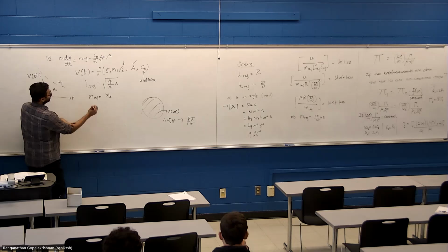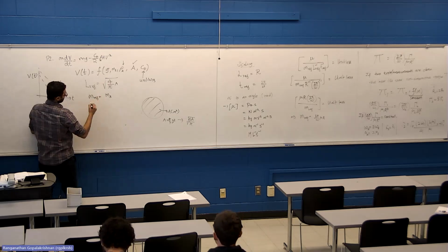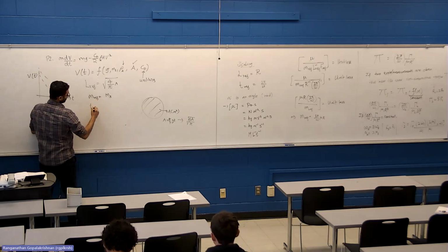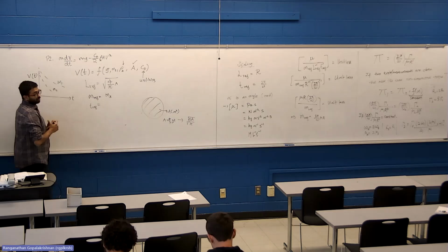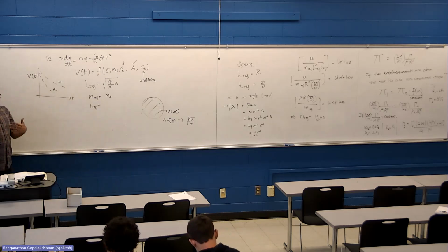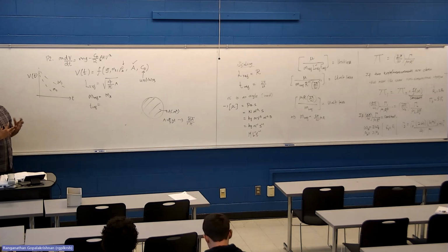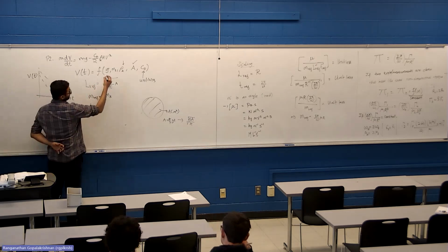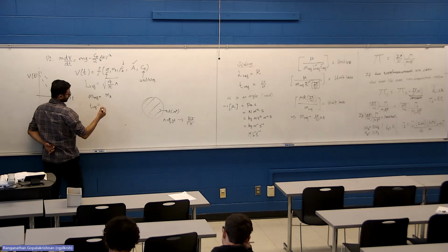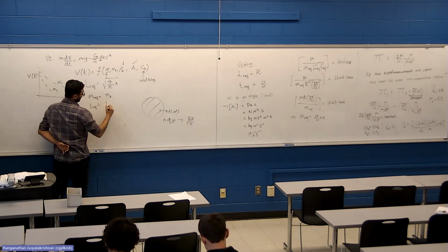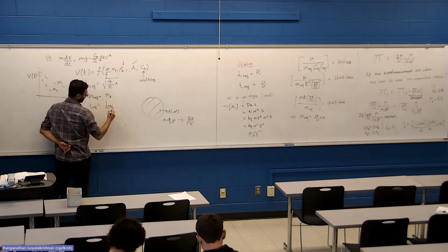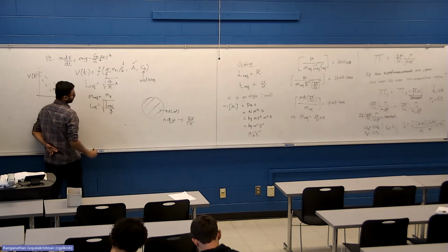Okay. So then, what is a good reference time? T is the real time that you measure with a clicker. But in this scale, what is the reference time that we can use? The only other quantity that involves time is G. So we would have L reference divided by G, square root.